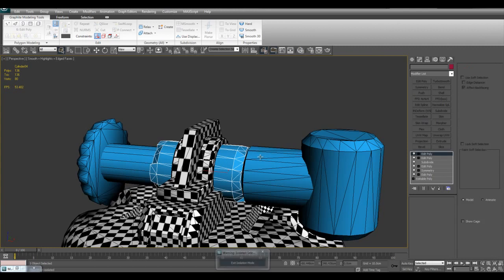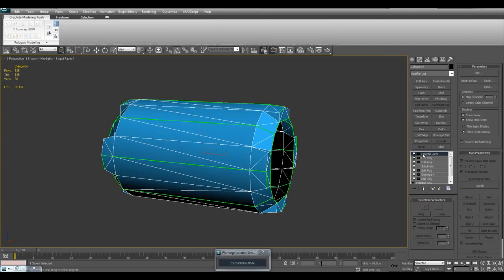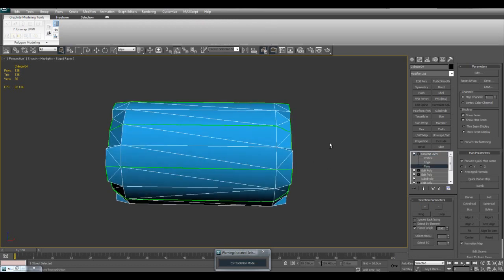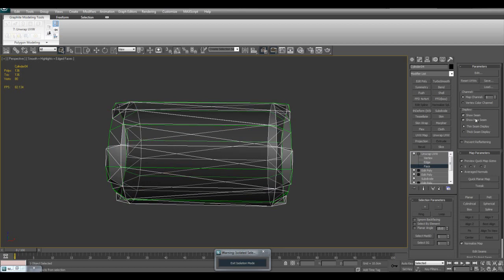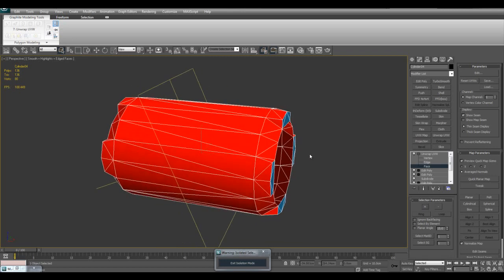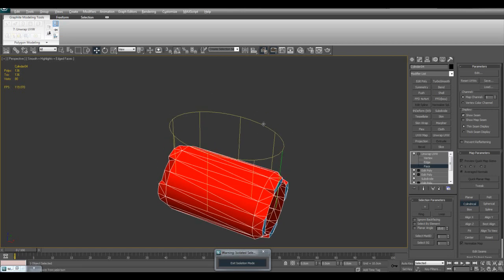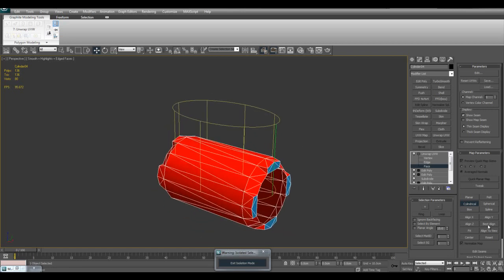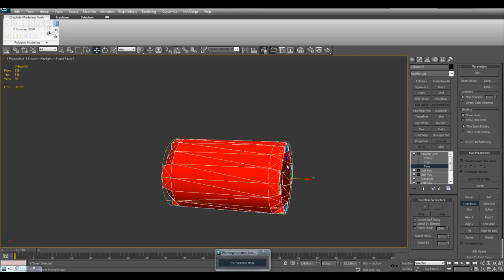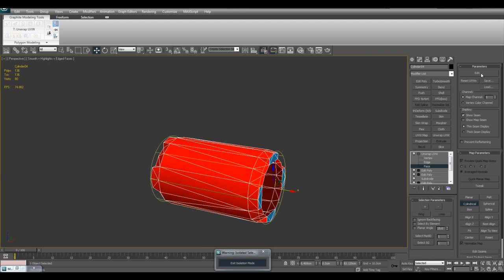And let's go ahead and work on this part. Let's go ahead and start with what I'll do. So I'll go ahead and select the middle. Let me see, plus to make it grow. Alright, use the cylindrical. You can see the cylinder here by default is in this orientation. So let's click on best align. That rotates the cylinder and aligns it to the position here.